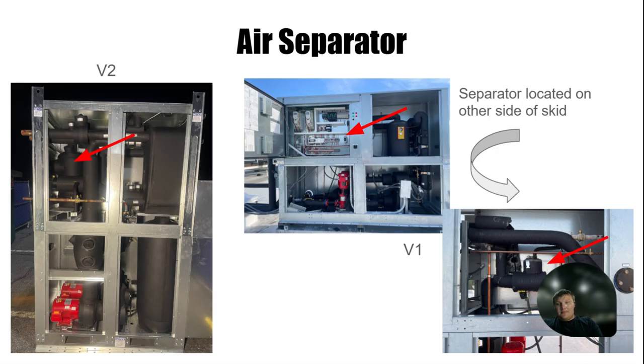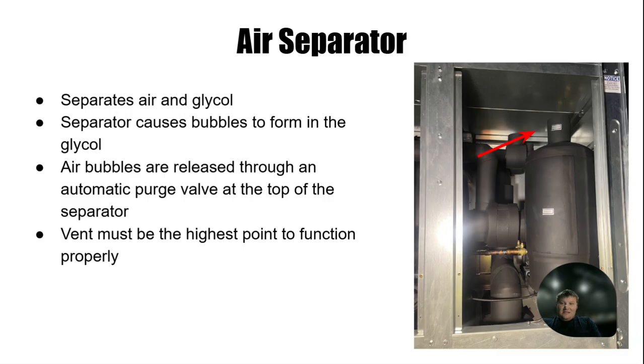Next is our air separator. And what that does is separate air and glycol. Inside this air separator, it creates a vortex and it causes bubbles to fall out of solution.